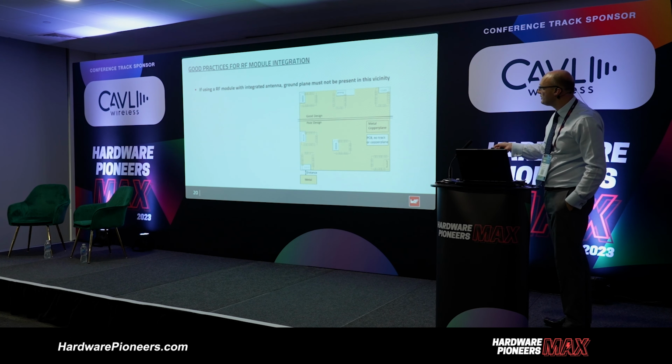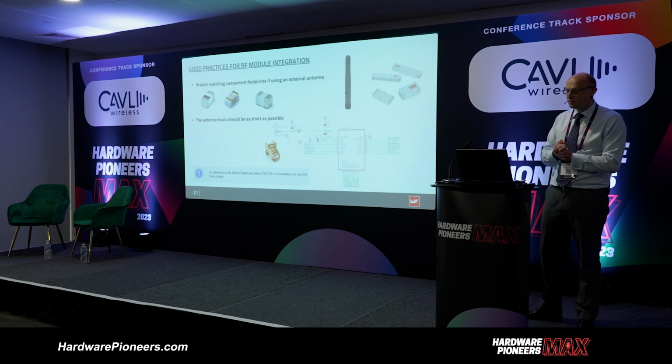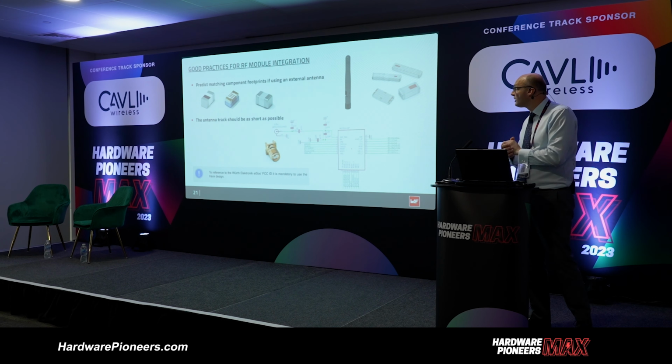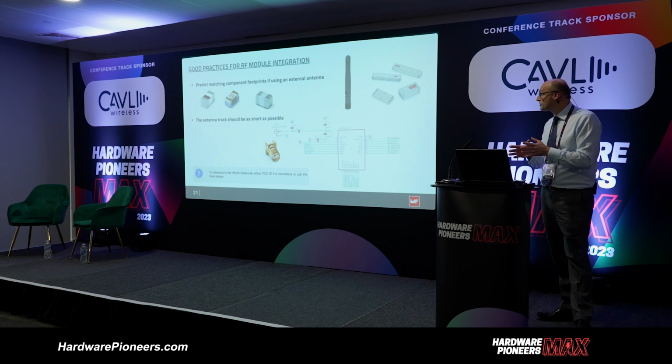So when it comes to antennas, certainly with external antennas, you may need to take into account additional antenna matching. Although the module itself, they may give you some guidance on additional components, be it inductors, RF capacitors, that you can now build into your actual circuit with regard to matching.